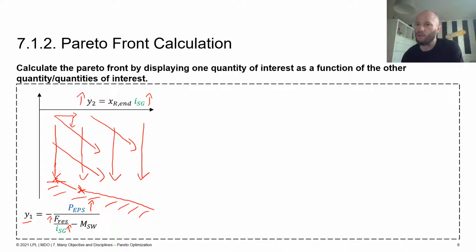Out of this we can conclude that our Pareto front consists of all designs with different gear ratios and the power of the actuator at the upper bound. And all of this within the design space of the gear ratio. So that means the gear ratio is supposed to be between 70 and 100.